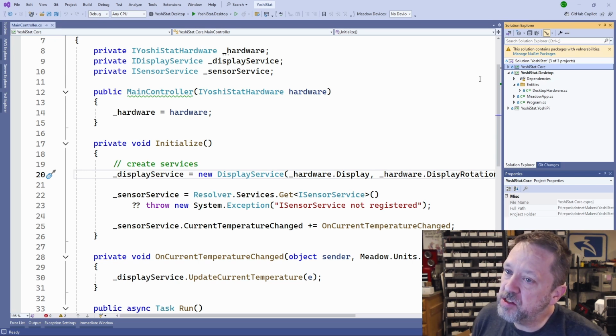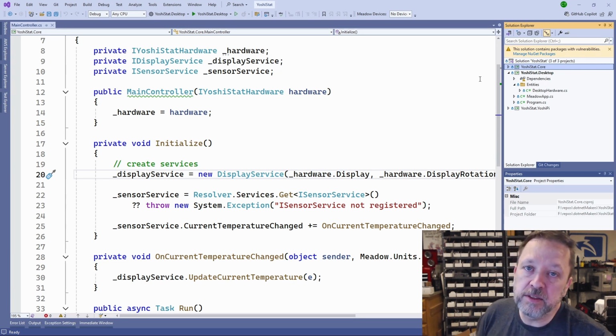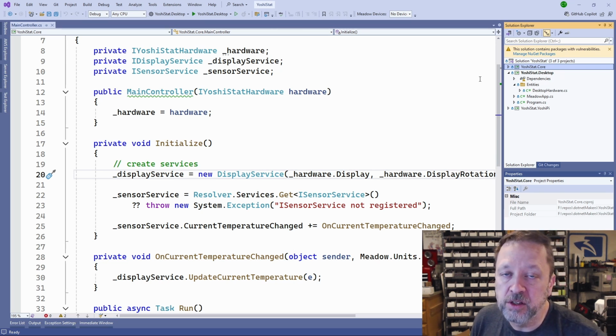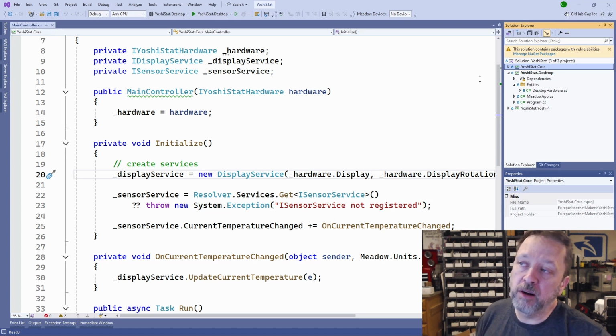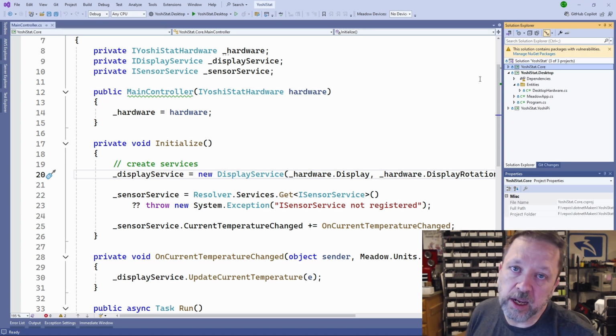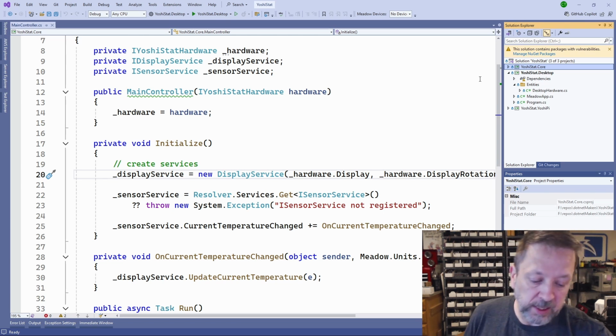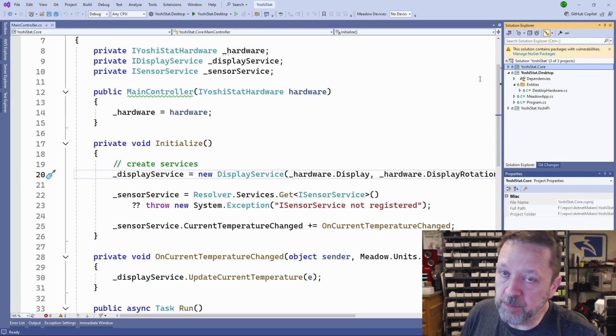So when your thermostat calls for heat or calls for cool, it sends 24-volt AC to the control board, usually in your HVAC unit. That's for something like a central air handler with a condenser and maybe burners or resistive elements for heat. It would be different if you've got resistive baseboards or if you've got steam, those kinds of things. I'm less familiar with how they work, so I'm not positive how the control systems on those work. So your mileage might vary on whether or not this would work.